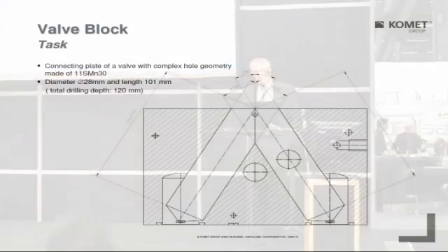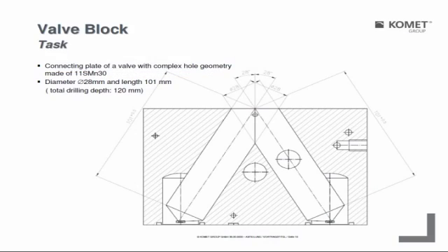Look at this task. It's a valve block. What you can do here is machine it with a milling cutter first. The entering section will be very critical because we have two holes in a V-type. And it's a manganese steel. Diameter was 28. The tool length was 101 millimeters, the boring depth 101 millimeters. But because we have to enter under this angle, how many degrees? 28 degrees. So we need a longer tool to cover the whole length of the bore.